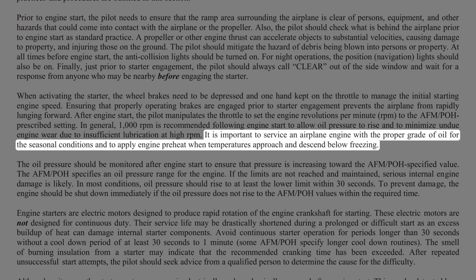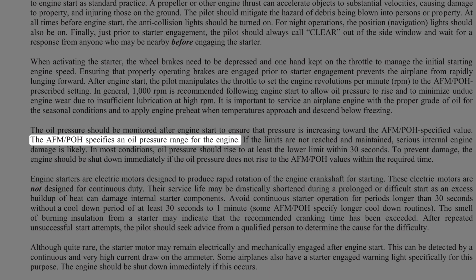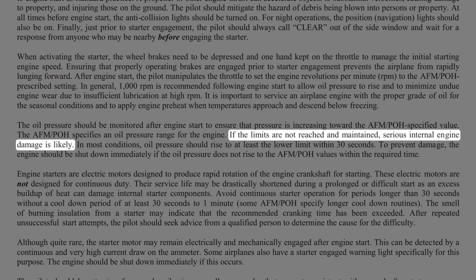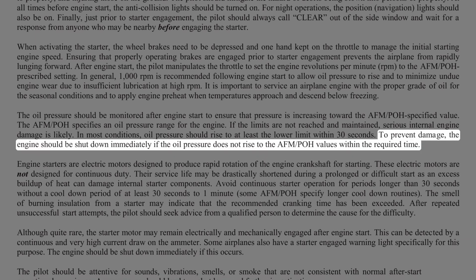It is important to service an airplane engine with the proper grade of oil for the seasonal conditions and to apply engine preheat when temperatures approach and descend below freezing. The oil pressure should be monitored after engine start to ensure that pressure is increasing toward the AFM, POH specified value. The AFM, POH specifies an oil pressure range for the engine. If the limits are not reached and maintained, serious internal engine damage is likely. In most conditions, oil pressure should rise to at least the lower limit within 30 seconds. To prevent damage, the engine should be shut down immediately if the oil pressure does not rise to the AFM, POH values within the required time.